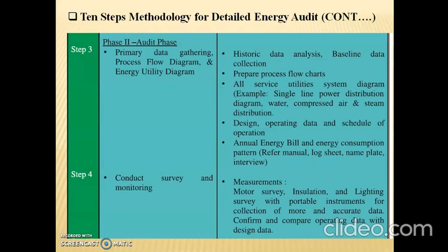Then design operating data and schedule of the operation. This is very important to have for conducting the actual testing on the instrument. Then annual energy bill and energy consumption pattern. For that, refer to the manual, log sheet and nameplate, and interview the actual operators in the field. So this is the third step.